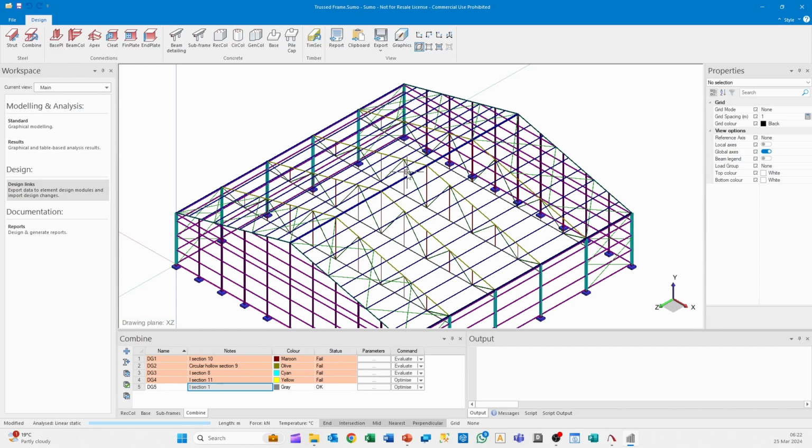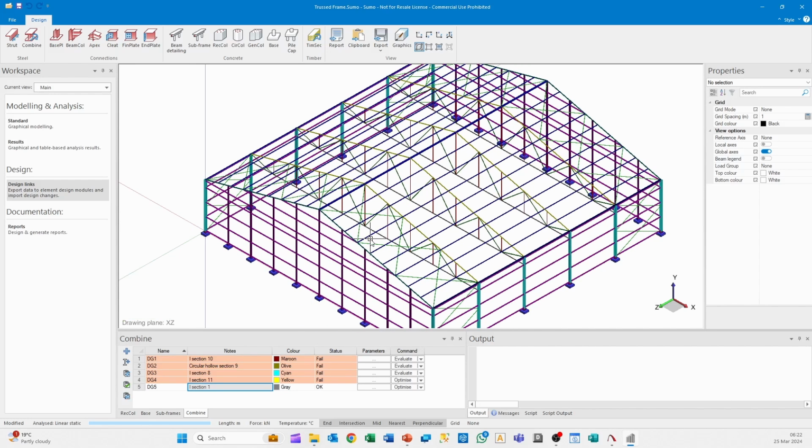cross-section of any element in the model, or you change any of the loading, the status here will go to out of date. And remember, as you optimize a model, optimization might not mean that the element is made smaller, but rather that the element is made bigger. That changes the loading characteristics of that particular beam, and it changes the model actually because it means that you have a larger self-weight. Okay, so it's best to do it in sequence.